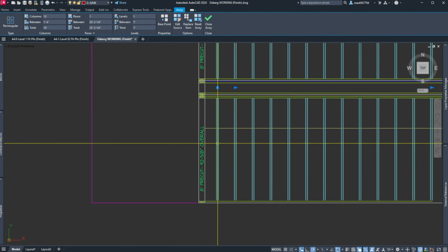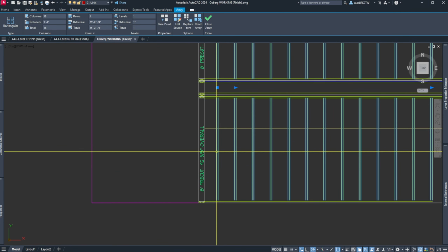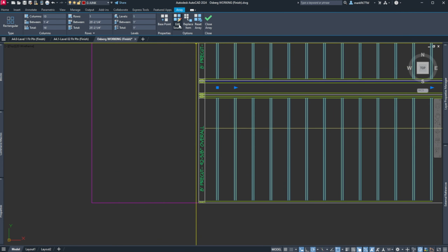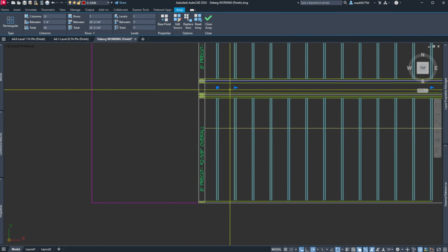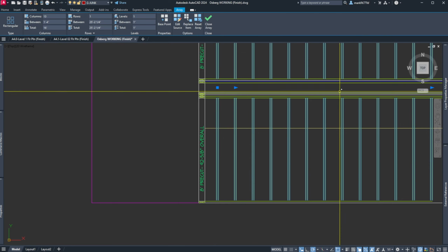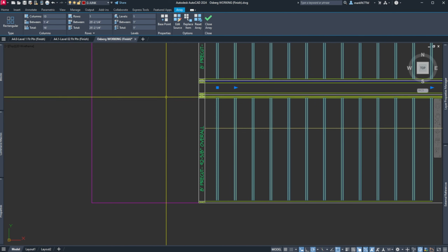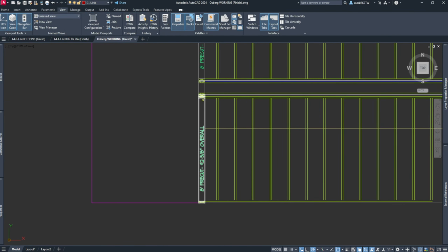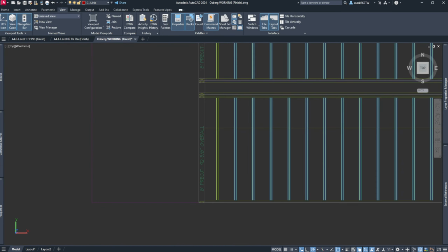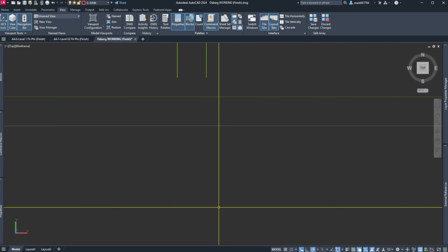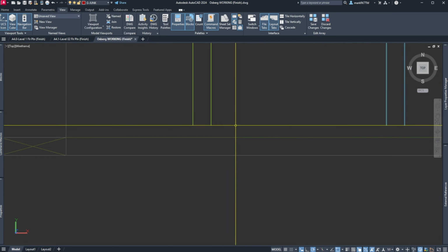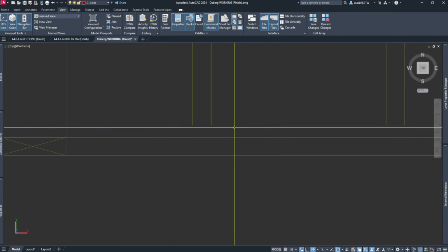And so to fix an array, little extra on the lesson now. Come in here, I'll hit edit source. Now that I double clicked it, you can see which way I drew it, because there's the square and then 2 arrows. There's the spacing arrow and there's the overall distance arrow. I'm going to hit edit source. I'm going to pick my source. An associated array, yes I do. And so I'm just going to tell it to extend to here.